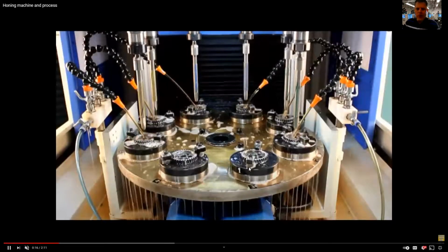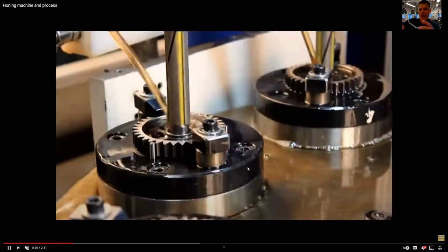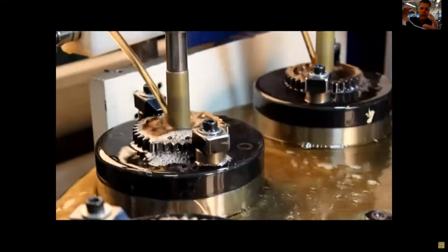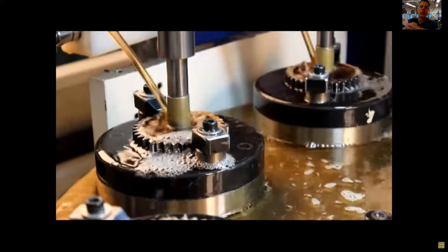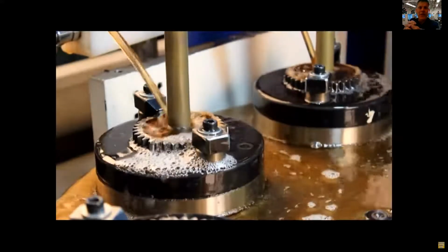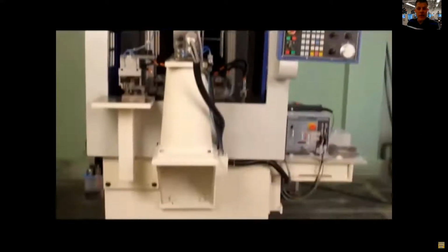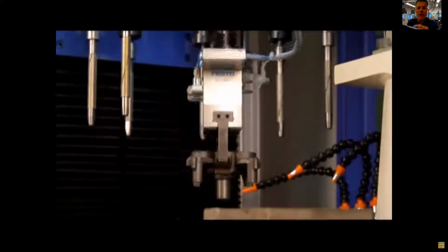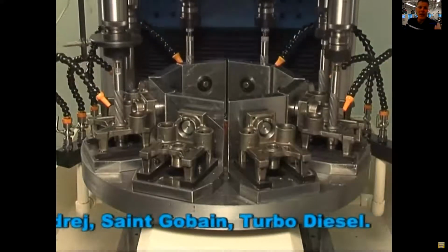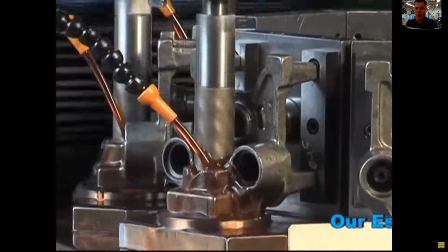Now, these gears are going to go on a tight tolerance shaft, and you're going to want to hopefully get maybe 100,000 miles out of your transmission, right? These are transmission gears. If you don't have a tight tolerance and good surface finish on that internal hardened gear surface that's riding on that shaft, it's going to gall itself over time. So you want hardened surfaces that have smooth and tight tolerances to ride over each other in a nice oil bath. That's what a transmission gear is all about. So they use this honing process to hone those internal bores.